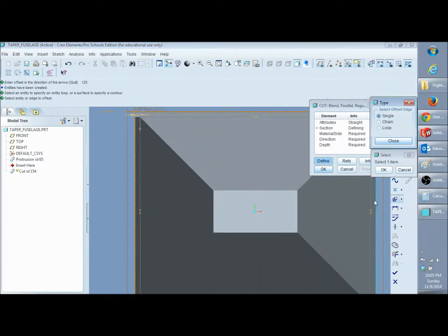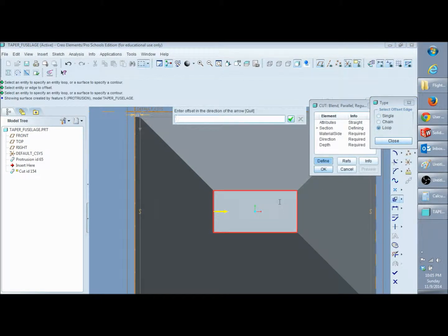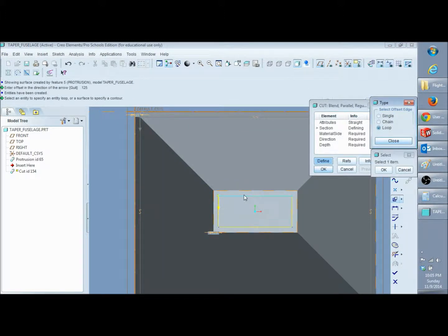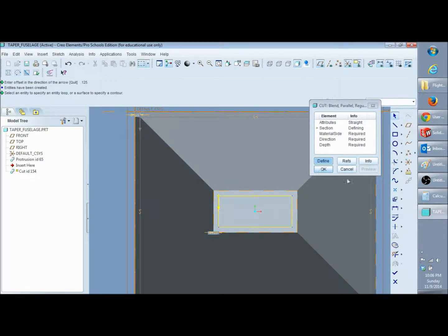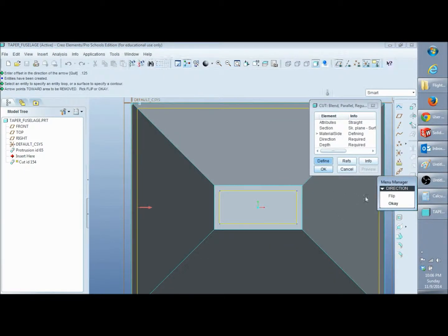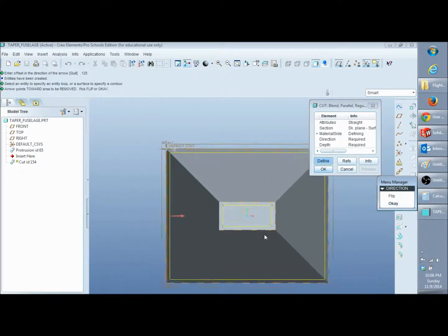So use the offset tool again to loop, and the arrow is pointing the same way again. 0.125, and keep it over your things over here now. So keep in mind where the arrow for the starting point is pointing, so it's all good. So, go ahead and hit close for those. The check mark here, and direction is good.